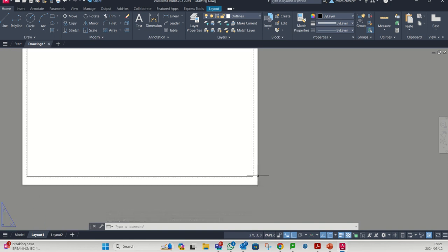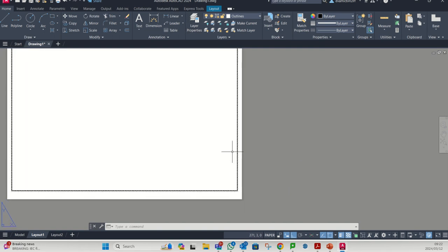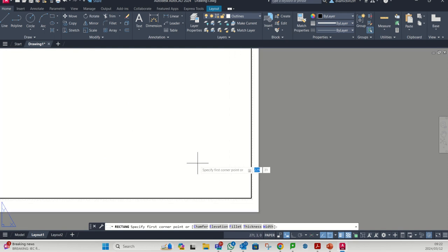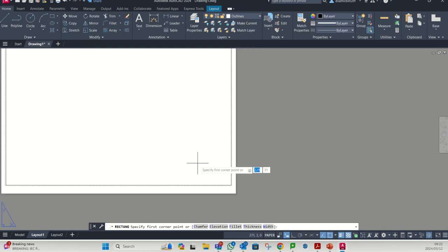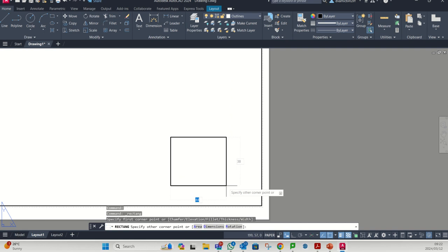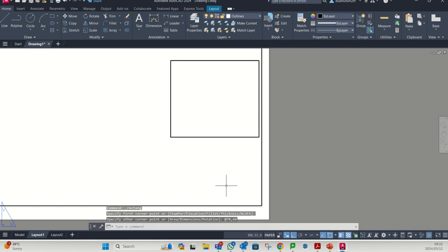The next thing we're going to do is create a little title block for us to draw in. We're going to use the rectangle command here. We really need lines for our name, for the worksheet number we're drawing, to say that it's an isometric, and the scale. So we really need 4 rows. Instead of using a table, we're going to go very manual here. So I'm going to go rectangle, and I'm going to go a total of 70 by 60 high. So 70, comma, 60, enter.